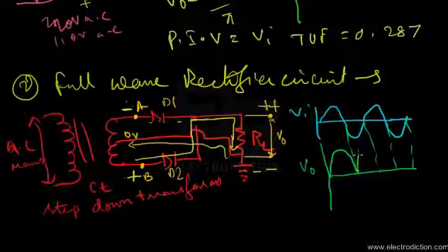So based on this conclusion, the output voltage waveform that we'll obtain over here would obviously be of the same type of waveform as that obtained in case of the first half cycle, as this second half cycle just gets inverted, and we get just the inverted replica of the second half cycle of the input AC voltage. Okay, so for the rest of the half cycles of the AC input voltage, similar things will happen, and we shall get a pulsating DC output that just looks somewhat like this.